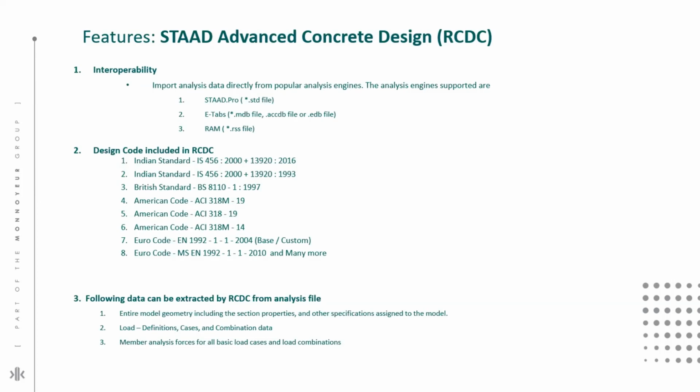The following data can be extracted by RCDC from the analysis file: entire model geometry, including the section properties and other specifications assigned to the model. Load definition, cases, and combination data. Member analysis forces for all basic loads, cases, and load combinations.